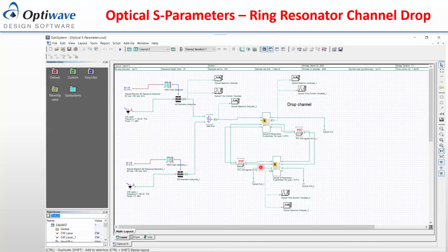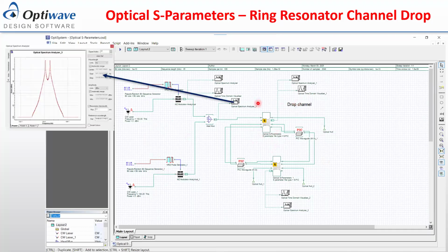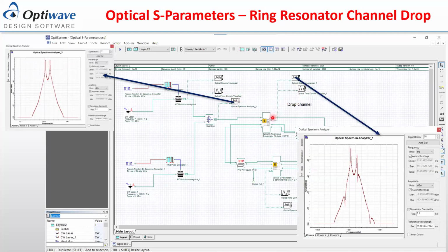Another example is, for example, here you have two DWDM channels, and you can use the ring resonator here. If you look here at the combined channels, then you can look at the through channel. One of these wavelengths, which is this wavelength of the laser, is going through. The other one is blocked because it's going to be dropped on this path here. And from here you can study the effect of crosstalk, how much is the ratio between the input and the other one, which is going to be leaking. So you have to choose your filters properly afterwards and so on.